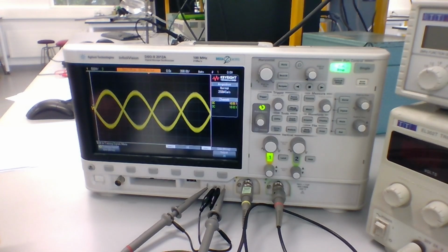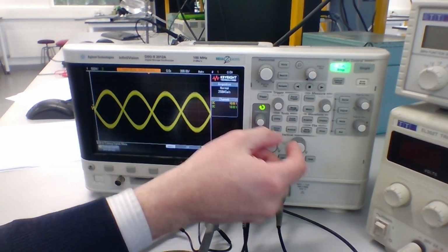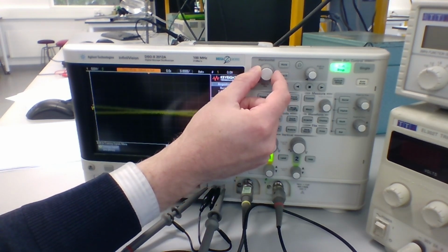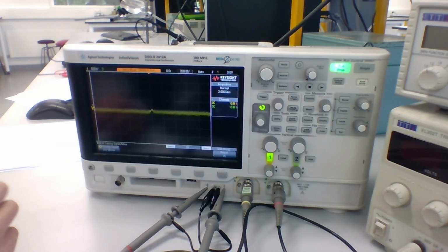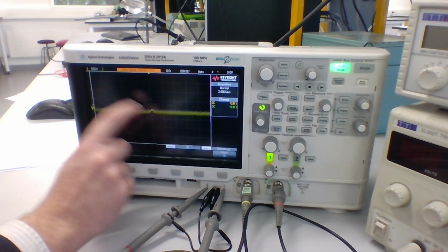What we can do is have a little zoom in and see what's going on and verify that the oscilloscope is in fact triggering on the rising edge. So when we put this back to the default setup, this puts the oscilloscope back to auto mode on a rising edge. So if we zoom into 200 nanoseconds per division in our time base, it's a little hard to see what's going on. What we're really looking at is noise, but there is a slight tick up there, which is our rising edge we're triggering on.